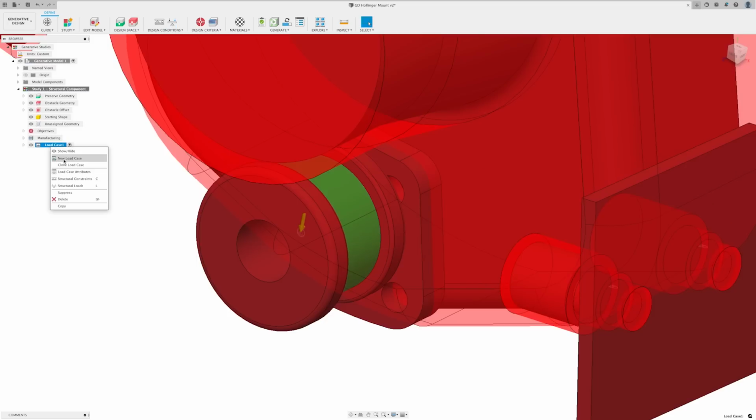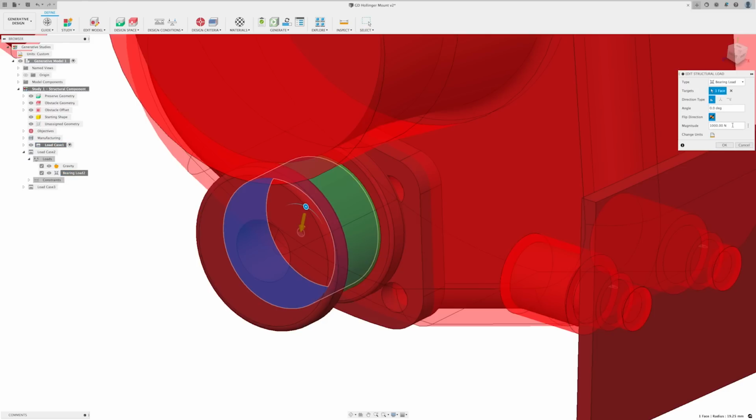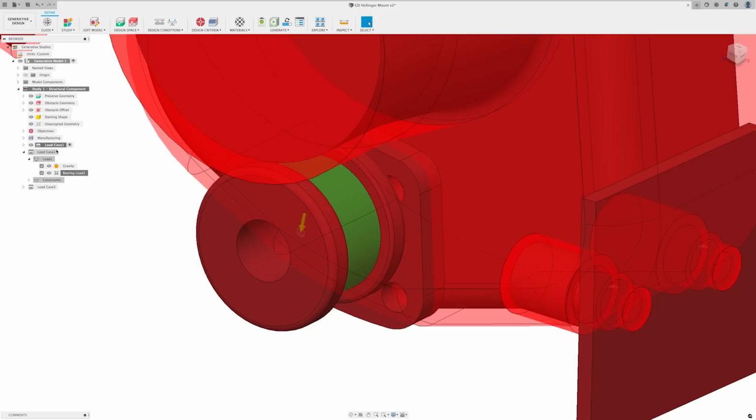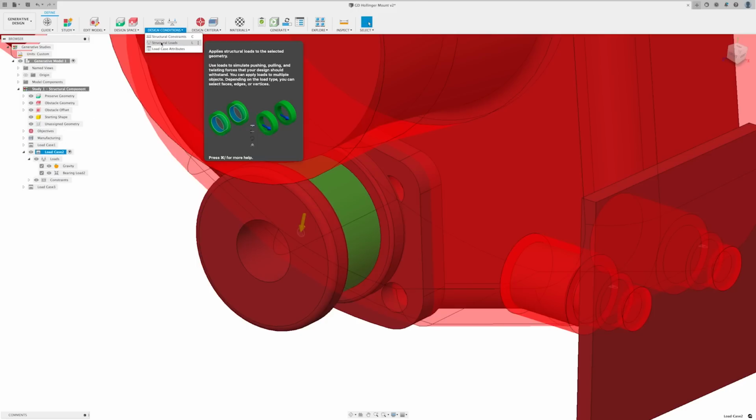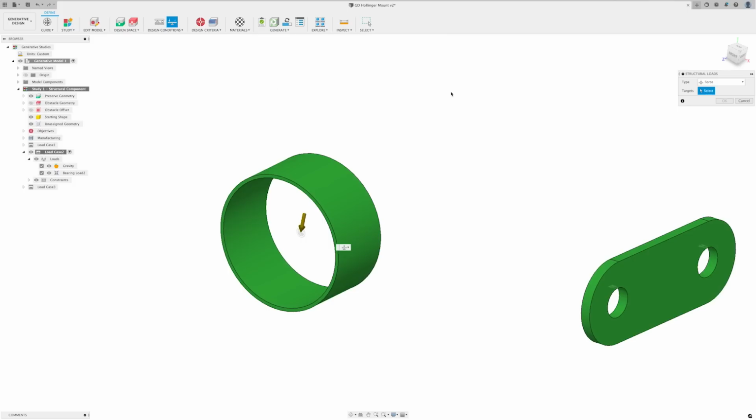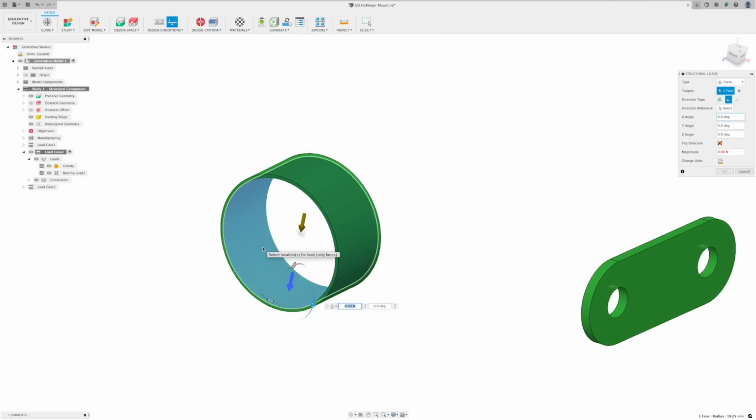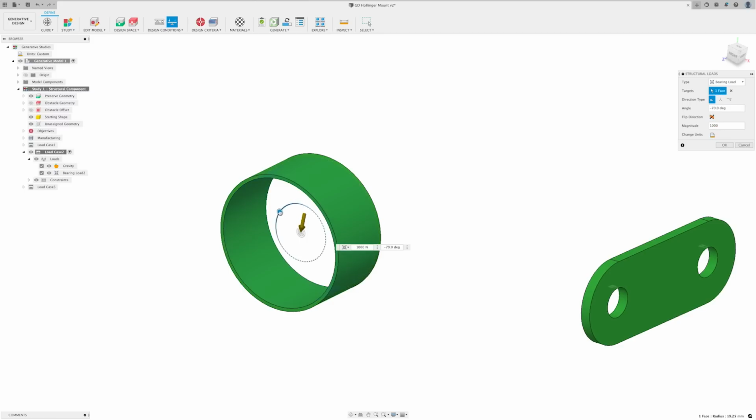After this, we can right-click to clone the load case twice, reducing the downward load to 500 Newton for each clone and also adding a 1000 Newton force to the left on one clone and to the right on the other. The 1000 Newton downward load case represents the load through the mount as the car moves through a harsh bump. The other load cases represent the load through a corner but also retain some degree of downward load.